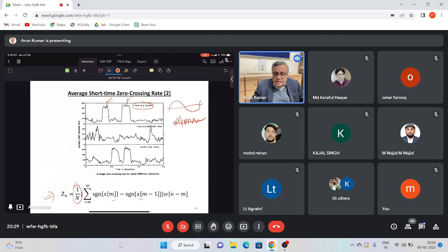So here again, because of the unvoiced segment, we have a higher zero crossing rate. And likewise, one can try to argue in the other figures regarding the unvoiced regions giving you a higher zero crossing rate. For example, if we look at the third plot, "what she said."